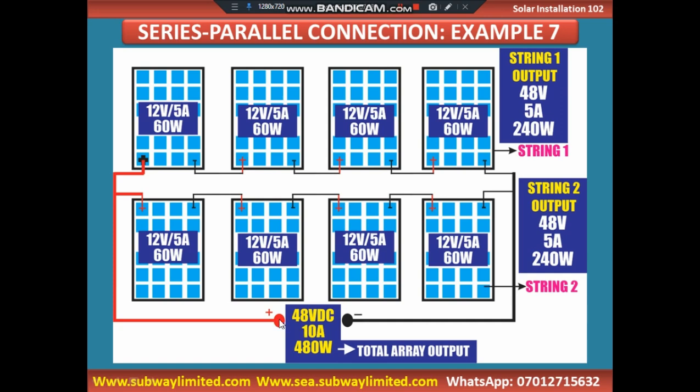If you have that, remember, the voltage will remain the same, because now we are connecting it in parallel. The voltage will not change. It will still be 48 volts. Since we are connecting it in parallel, remember we first connect them in series and keep. Then now we come and connect them in parallel.